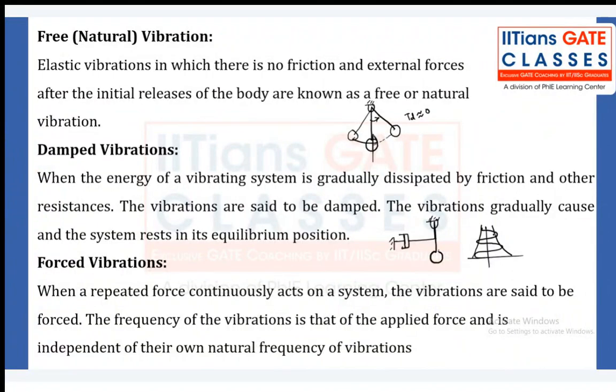Third is forced vibrations. When there is a repetitive force continuously acting on the system, then the vibrations are said to be called forced vibrations. Right. And the frequency of the vibration is that of the applied force, and it is independent of the natural frequency of the system.